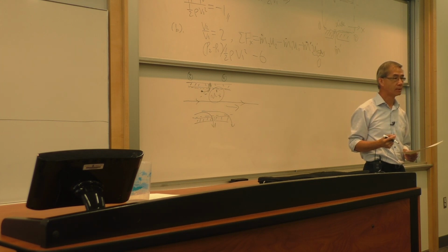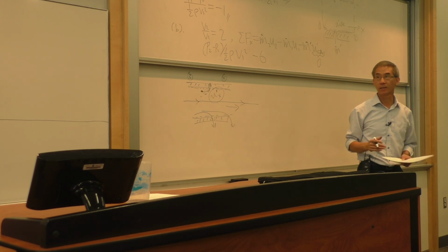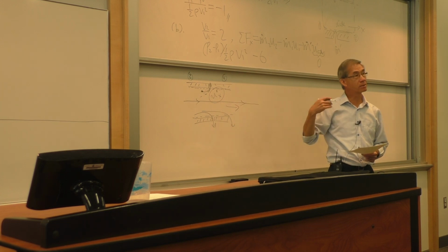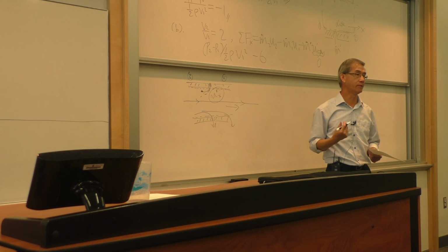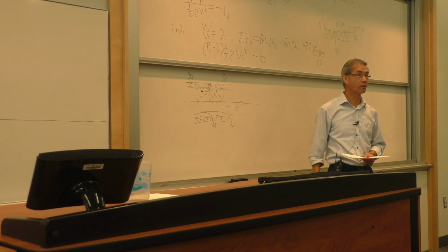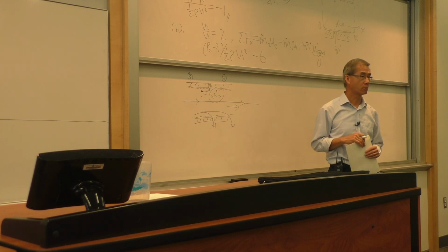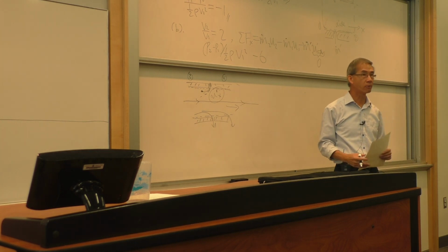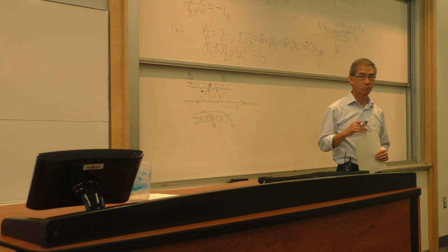If you were maybe given an anchoring force, could you then? Yeah. I chose the control volume internal to my wall for that reason, because no anchoring force was mentioned or given to me. So I want to avoid having to deal with anchoring force. And by choosing the internal control volume, I succeeded in avoiding that. That's a little tricky and not typical of the problems we have done in the past for homework. So that's a very good comment also. If you choose the control volume cutting through the wall, then the anchoring force will be present. There's no way of knowing what it is. Okay? So a little tricky from that standpoint and not traditional.